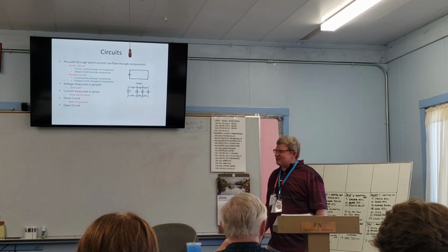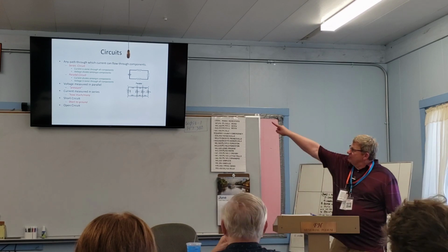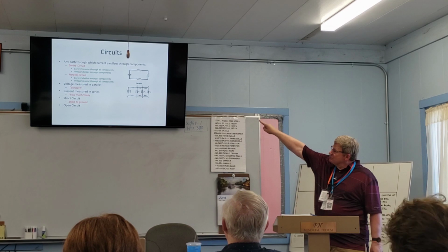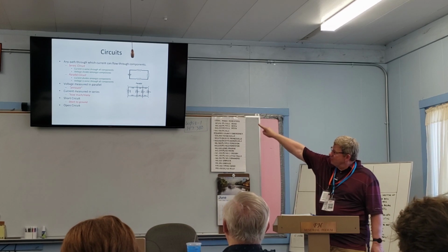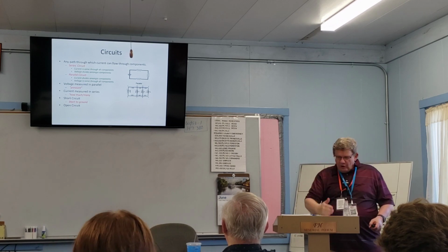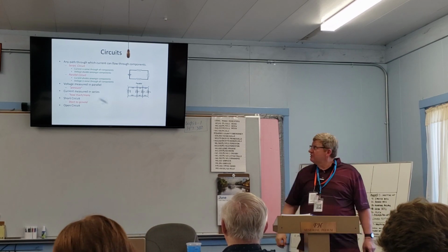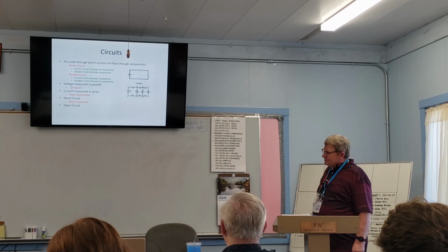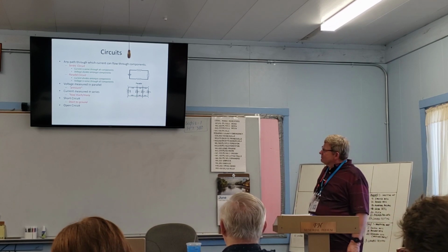And when they talk about series, it's like Christmas lights. That's an excellent example. It's the top picture there. It's coming up, it goes through one component, it goes through the next component, it goes through the next component. That's a series, one right after the other. Your amps increase? No. Current, amperage, is the same. Voltage increases.